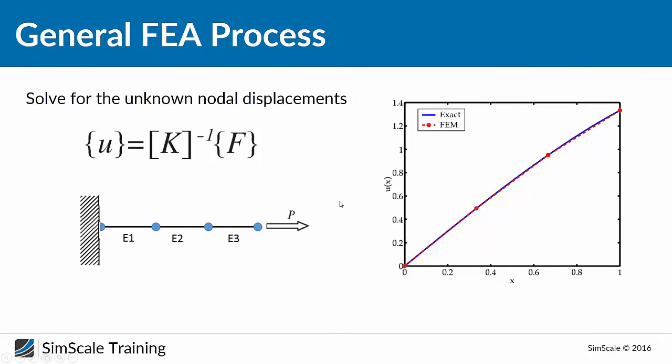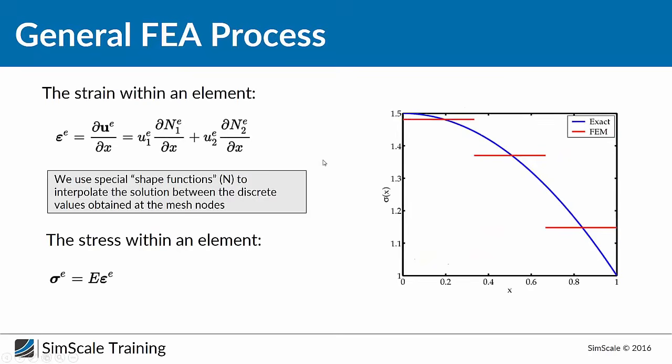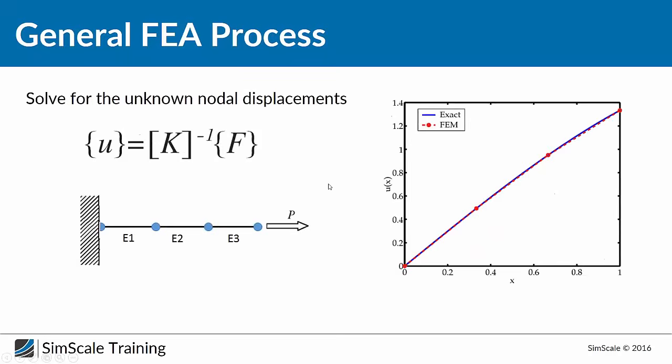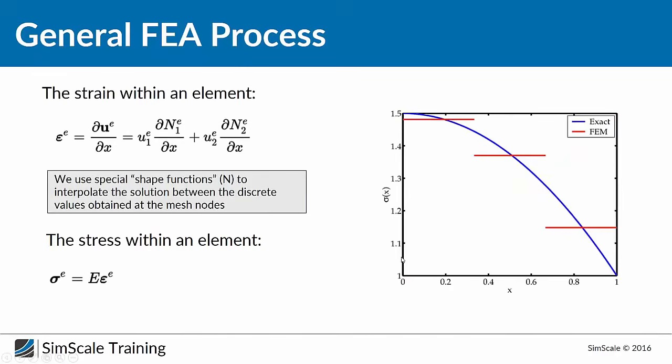But there are some things we have to consider, because we cannot take the solution without taking a look at it and trying to understand what is basically happening. The big difference between the analytic solution and the finite element solution is that the analytic solution is defined for every point in the range of X, while the finite element solution is only defined in the nodes.